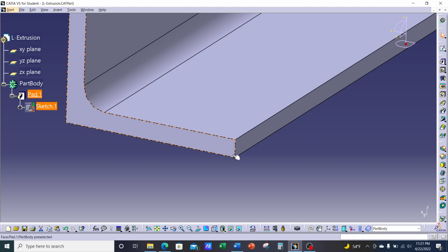Alright, so I'm going to round this corner. And I mentioned this before, typically chamfers, straight cuts, or fillets are intended to get rid of sharp edges. So anytime somebody's handling this part or it is being assembled, being attached or bolted to another part, one thing you don't want is sharp corners that can damage the other part or even harm the technician's hands. By the way, in the shop they call these sharp corners knuckle busters. Okay, so to avoid any damage or injury, we round off the corners. Okay, so we're going to create a fillet. So edge fillet, so click on fillet.